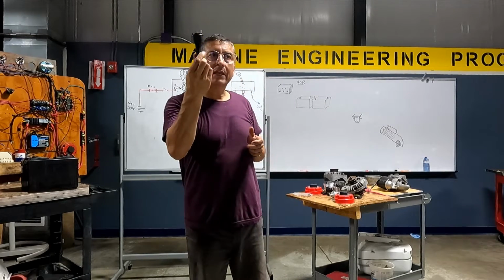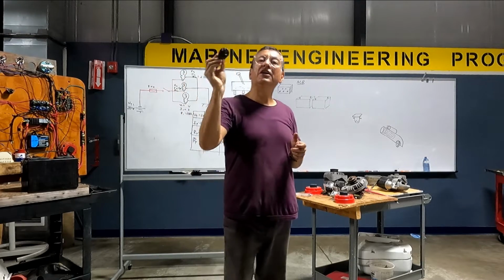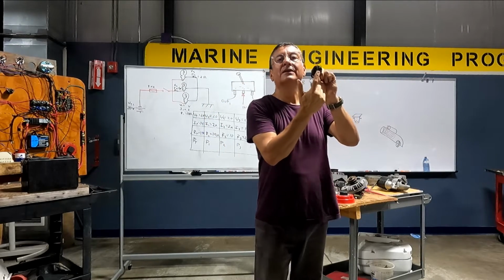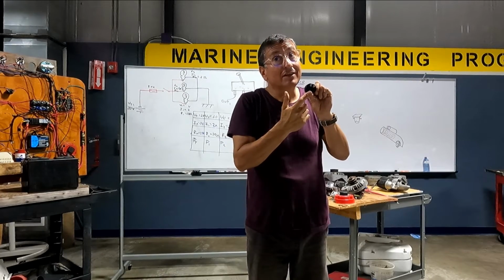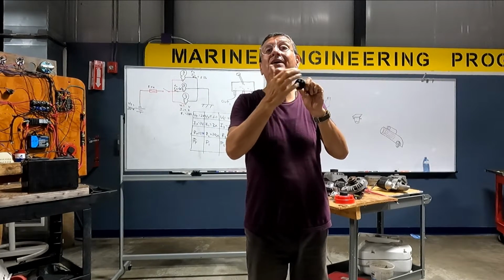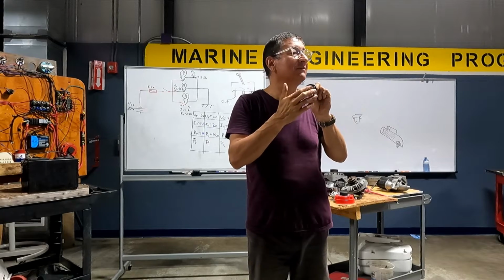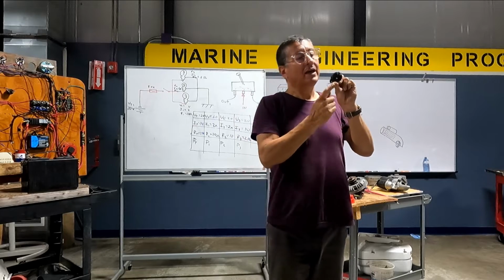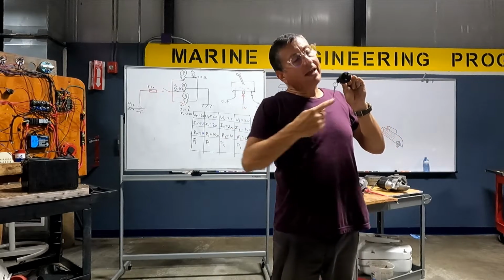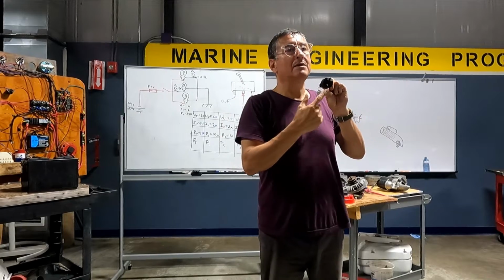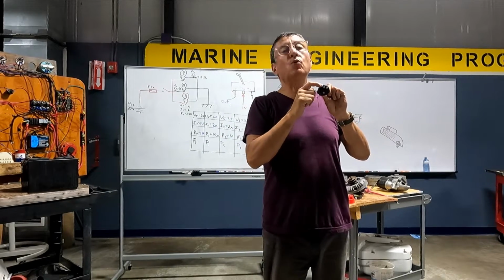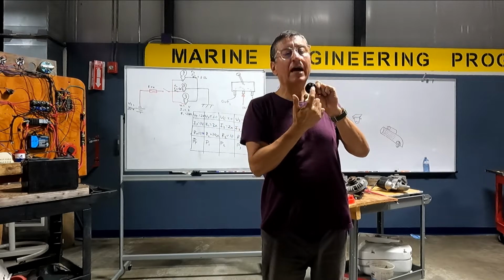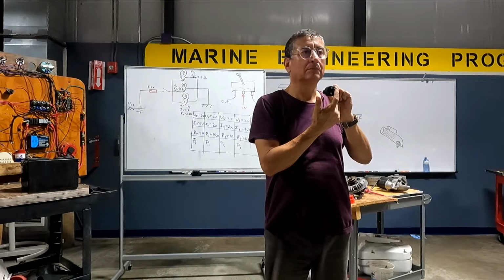Now we are going to explain the ignition switch. The ignition switch has three terminals. You see? Three terminals. It's a switch. Here you only have positive cables because it's a switch. I interrupt, or I send to here or to here. The power enters in position B, battery, and has two outputs. One output is I, ignition, and the other one is S, signal.